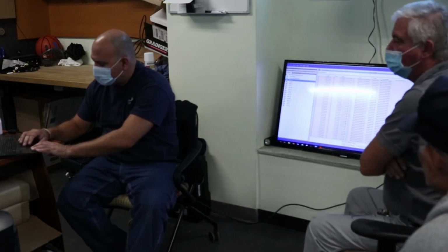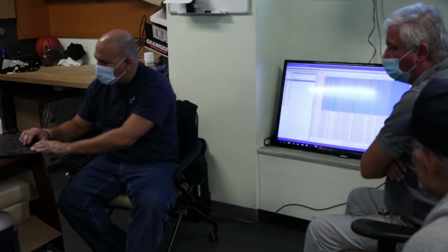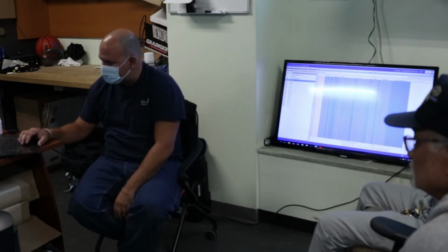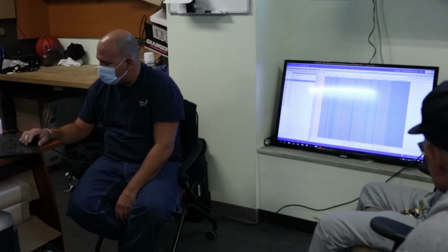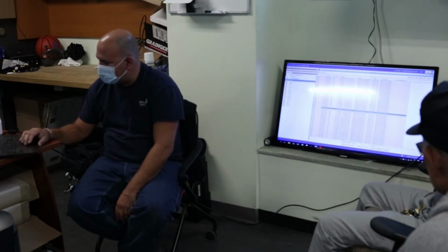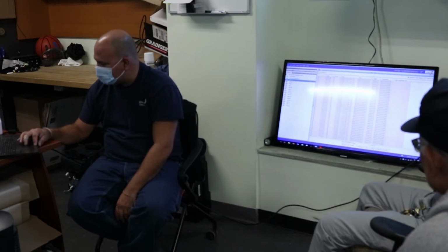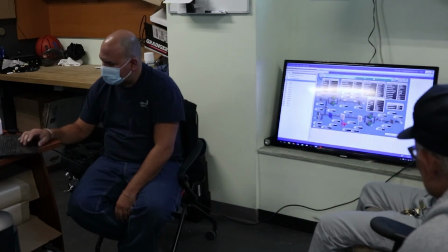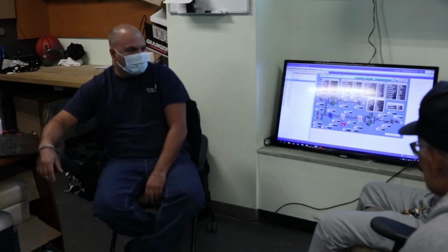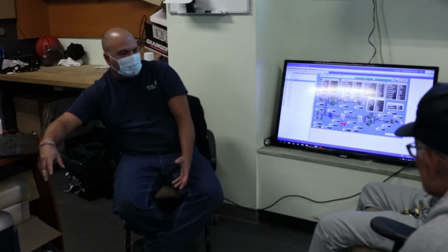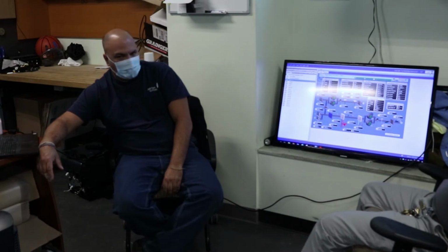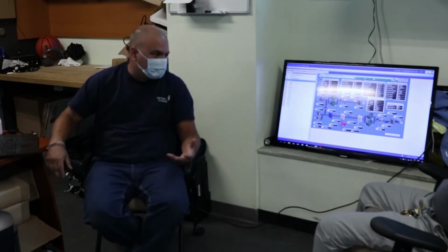You could also hold the mouse and slide down and do them like that. The Control A will take the whole page. It's quicker than acknowledging them one at a time. Typically I don't discard any alarms. I just acknowledge, and then your maintenance guy should purge out the system every 6 months or so. Just clear the cache and start from scratch.